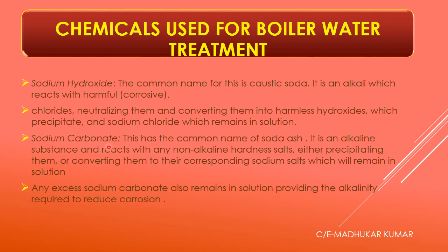Okay, sodium carbonate, this has a common name of soda ash, and it is an alkaline substance and reacts with any non-alkaline hardness salts, either precipitating them or converting them into the corresponding sodium salts which will remain in the solution. Any excess sodium carbonate also remains in the solution, providing the alkalinity required to reduce the corrosion. So basically this also is going to contribute towards the corrosion protection part of it.